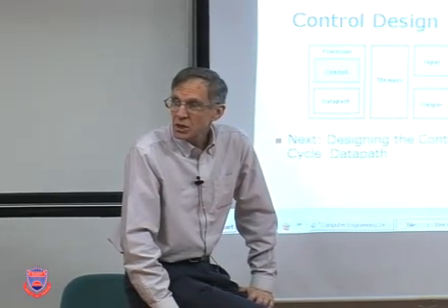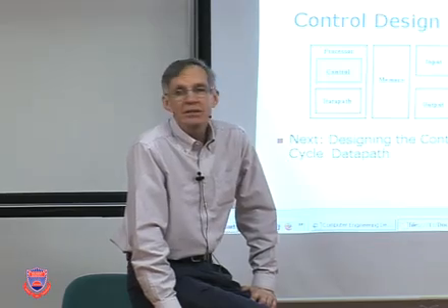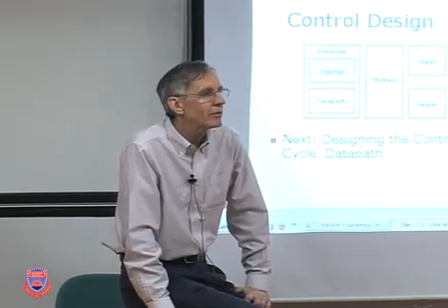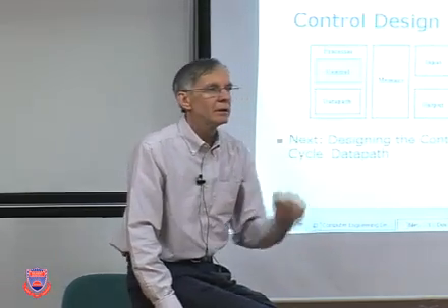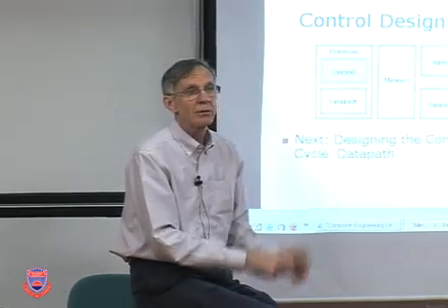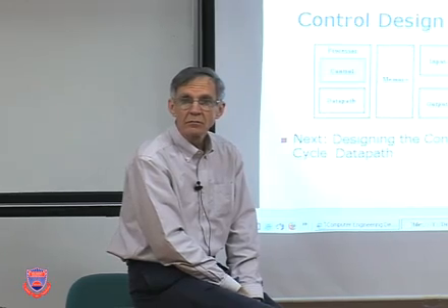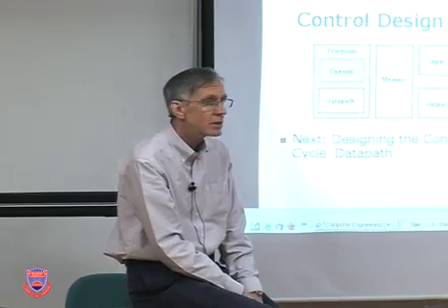When we got to branch and jump, we realized we better do something a little more intelligent than just add 4 to the PC, because we won't be able to branch or jump if that's all we ever do. We'll just go in sequence. So we added some instruction fetch unit hardware as well, or next instruction unit hardware. When we got it all done and put it together, we saw that actually it's understandable.